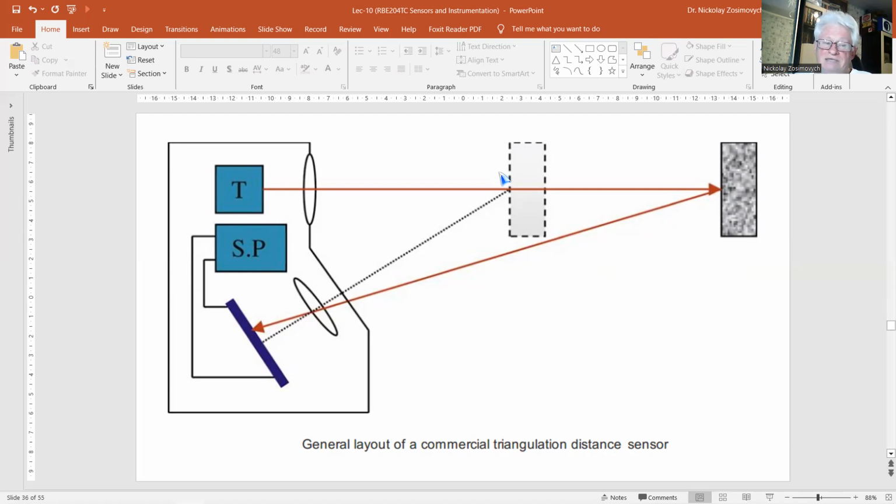systems based on triangulation. An example of a technological solution to miniaturization is where the LIGA process, German for lithography, Galvanoformung und Abformung, is applied to realize the required optical structure.